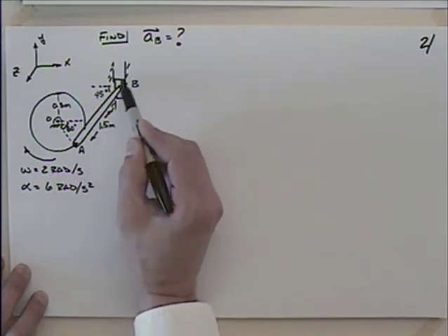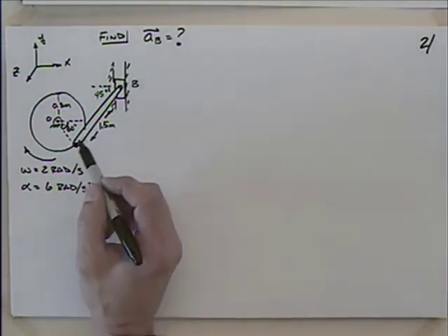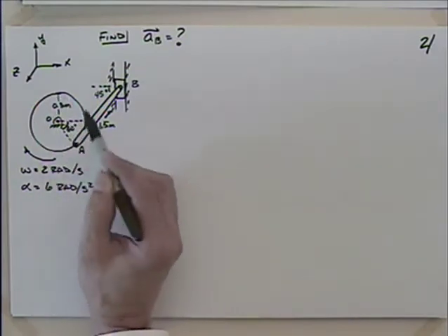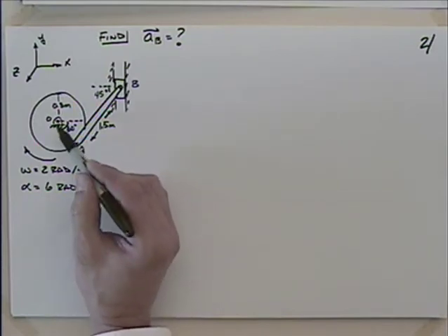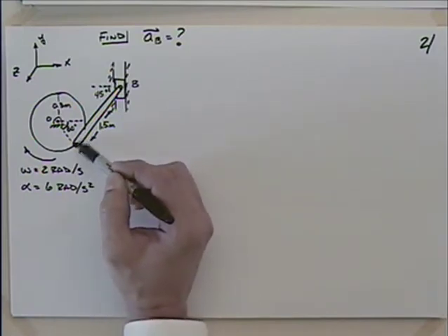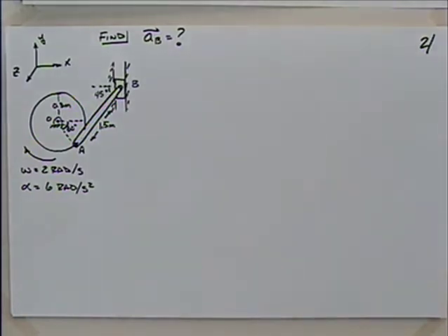And it's attached to this piston in this bore at B. So this is really a lot like an engine and connecting rod arrangement. If you look at this point A, that would be like riding around on a crankshaft, right? The crankshaft has some stroke, so we'd look at that 0.3 meters. Then we'd have the connecting rod, A to B, and we would have the piston then constrained in that bore